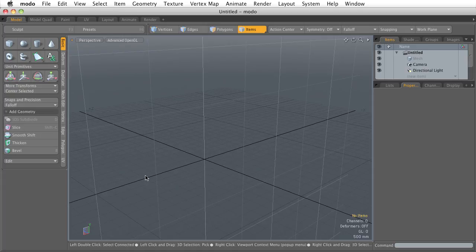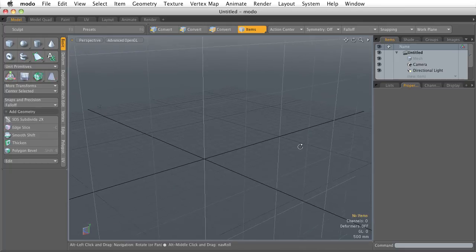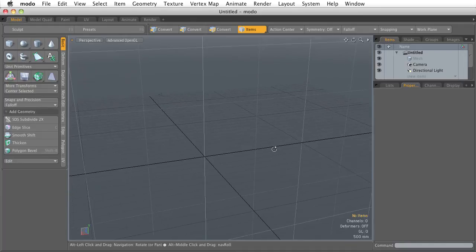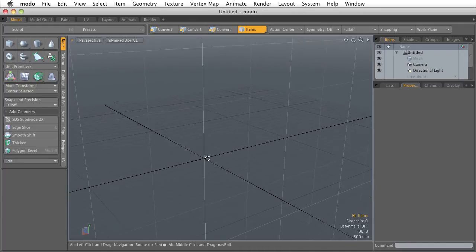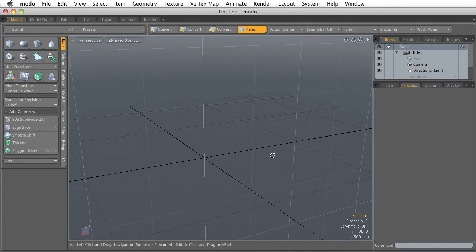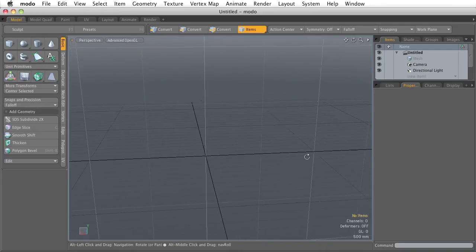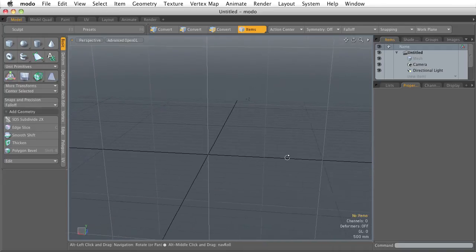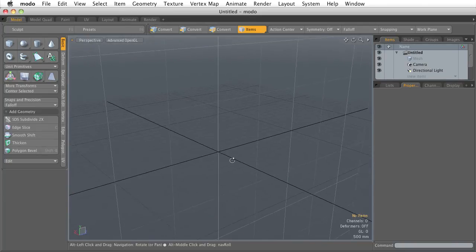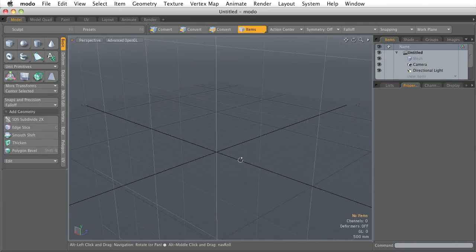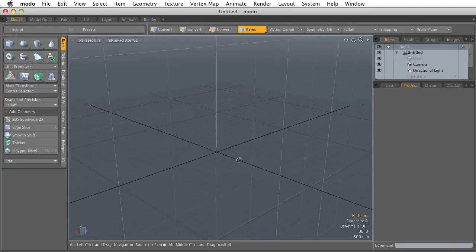And what makes the workplane so powerful is that it's an interactive snapping guide when we're using our modeling tools, and actually a lot of tools inside of Modo. And it's interactive because wherever we rotate our scene, the workplane is going to change its position. I just have the orbit tool held down right now, and watch very carefully, because when I continue to orbit around, it's going to snap to a different plane in a second. There it is. See, it snapped right there. See that changed perspective?